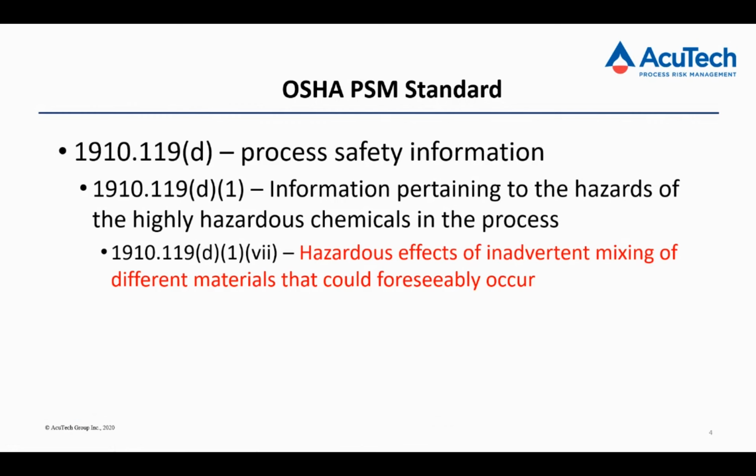So today, we're going to spend the majority of our time talking about one case study that the Chemical Safety Board did for an event from 2016 at MGPI Processing in Atchison, Kansas. We're going to look at some lessons learned from that incident, and then we'll talk about some ways to incorporate your inadvertent mixing information into your process hazards analyses. But first, I'd like to take a look at some other inadvertent mixing incidents and also how your inadvertent mixing program can be put together, organized, and used.